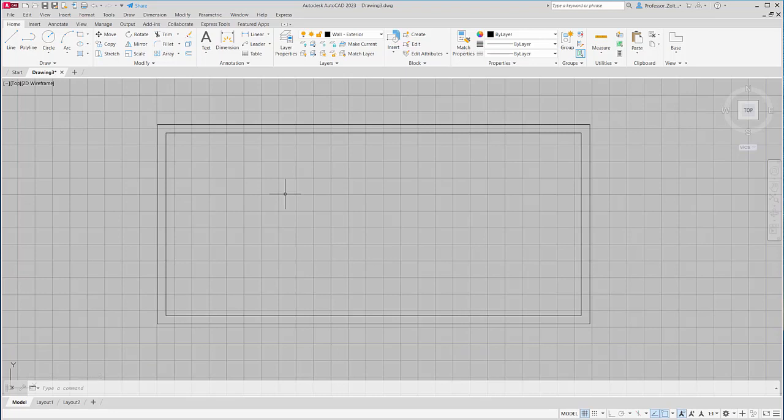So I'm looking at my project, and I'm going to create a number of different horizontal and vertical lines and then work within it to create the inner walls. Now, remember I have two sets of layers, exterior and interior. When you use a modify function, it takes on the property of the existing line. So I'm going to click on this outer line. That was the first one I had drawn, and you can see it says wall exterior. If I press escape and click on the inside wall, it also says wall exterior. So how am I going to make these interior walls using offset? I'm going to use the existing walls and then change their properties afterwards.